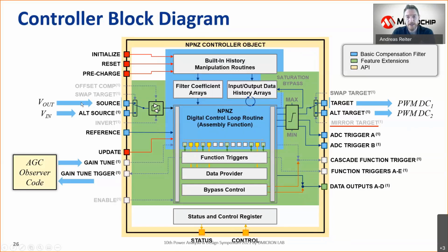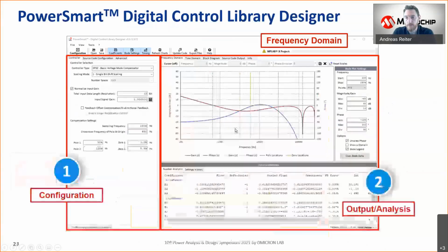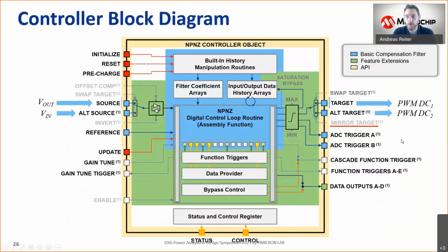That means when the computation inside our filter reaches a point where we need to incorporate the tuning factor, we are calling an external function which performs the adaptive gain observer code, determines the next tuning factor, and that tuning factor is then fed back into our computation loop, and then we are producing the next control output. Good.